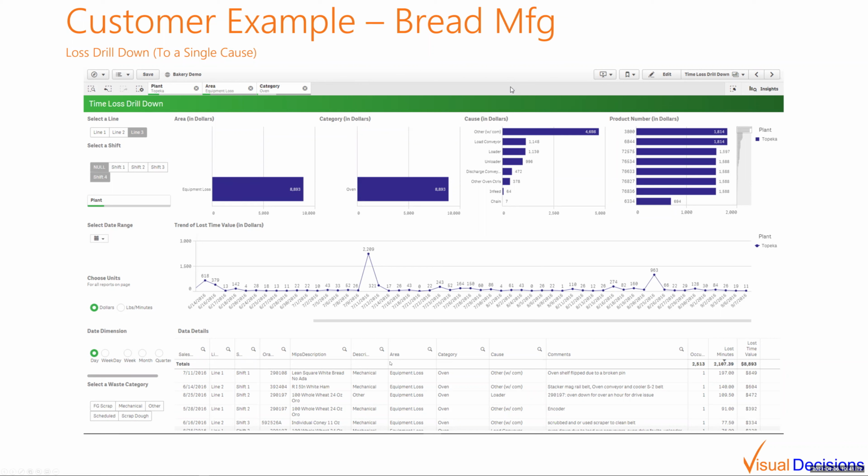And what we were able to determine very quickly by capturing some additional information when those did occur is that the pins that were holding the conveyor and so forth would fatigue in the oven as they heated up and then cooled, and heated up and then cooled, and so forth.